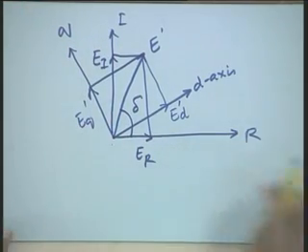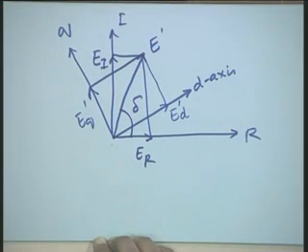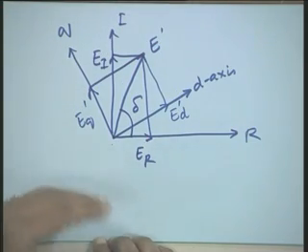Therefore, there are two important points to sum up here. One is that this E prime remains constant when you make this assumption. The second point is that the position of this E prime with respect to the q axis is fixed, and therefore I can measure the angle between E prime and any reference frame for performing my stability studies.